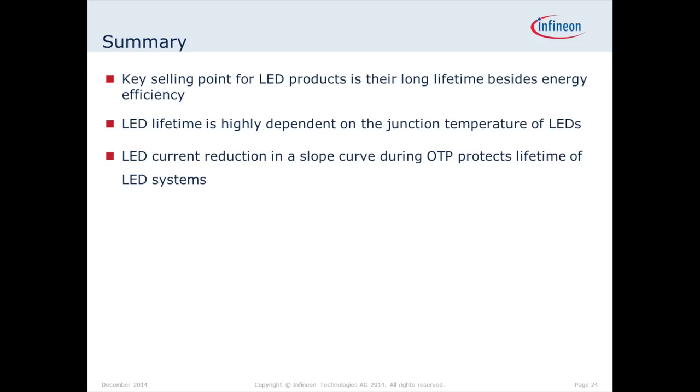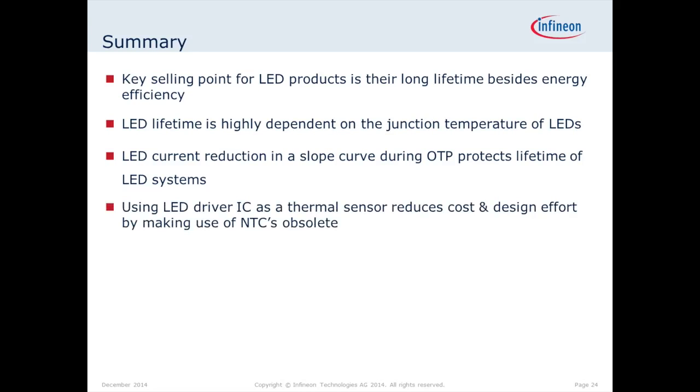As I've shared with you, of the energy put into LED systems, more than 50% goes into heat. Implementation of a slope curve for over-thermal protection ensures not only the lifetime of the LED driver IC, but also the lifetime extension of the LED system. If you can use the LED driver IC as a thermal sensor and don't need to use an NTC, this reduces not only your cost, but also your design effort, and helps to save some space on your PCB.